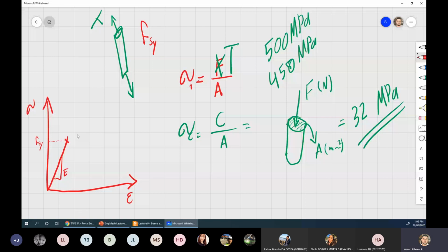So imagine there's a beam and you apply a load on it. After the load is gone, the beam stays sagging or bent. That's not a great design, correct? So that's the yielding point. After that yielding point, this relationship is not linear anymore. This part here is linear. As you can see, it's a sloped line, and the slope is the elastic modulus. But after that point, the relationship is not linear anymore.